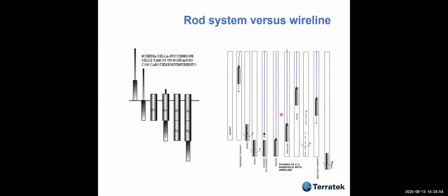hard rock sampling. And there are mainly two ways of doing that. One of them is by using a rod, okay? But if you are going very deep, you certainly need a wireline procedure or device in which the sampler is lowered into the borehole by means of a wire line, and then you pull it out. You start the rotation, and then you pull the sample out.